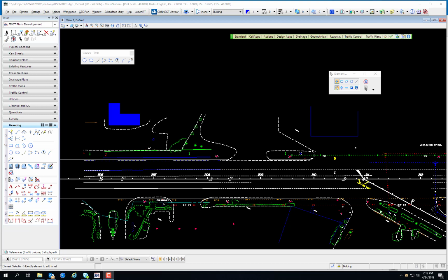The topics include locks, snap modes, AccuDraw, and AccuDraw shortcut key-ins. The tools discussed in this chapter are used in conjunction with drawing tools to create drawings with greater precision. These tools control accurate placement of elements by locking or constraining various settings. The first one is locks.